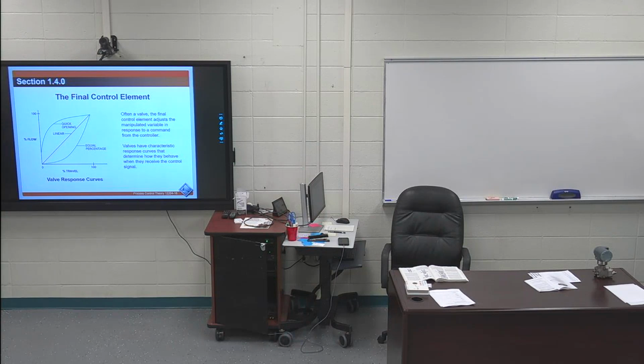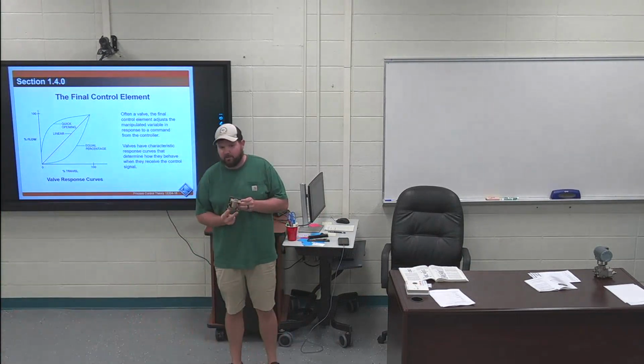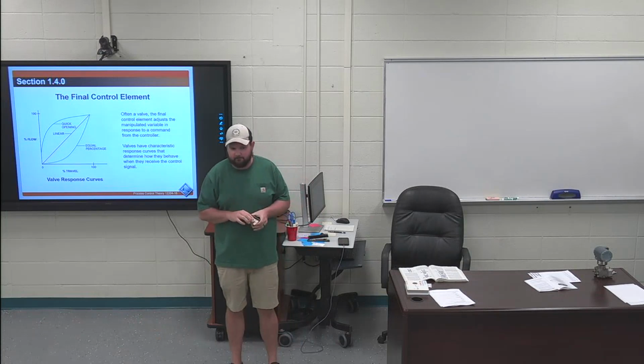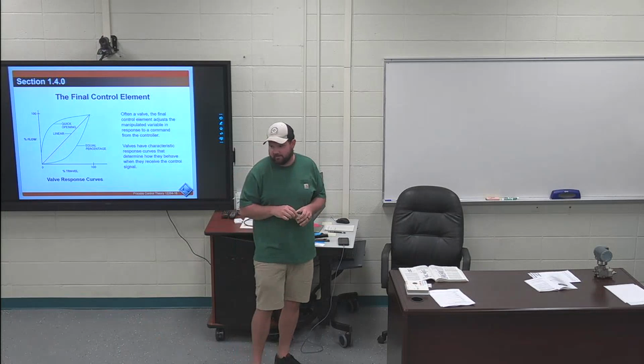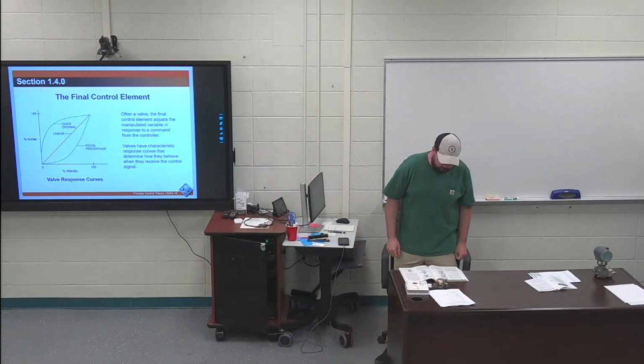So this is a solenoid core is essentially what it is, but it can also be a valve. You remember whenever you put current through this, this is just a coil of wire, it induced a magnetic field, then took this and sucked it in there, right? So a solenoid valve works the same way. It can be open as soon as I energize it. It can slam closed and shut off, turn on or off flow through that pipe. That makes sense? So just a very simple piece of equipment.